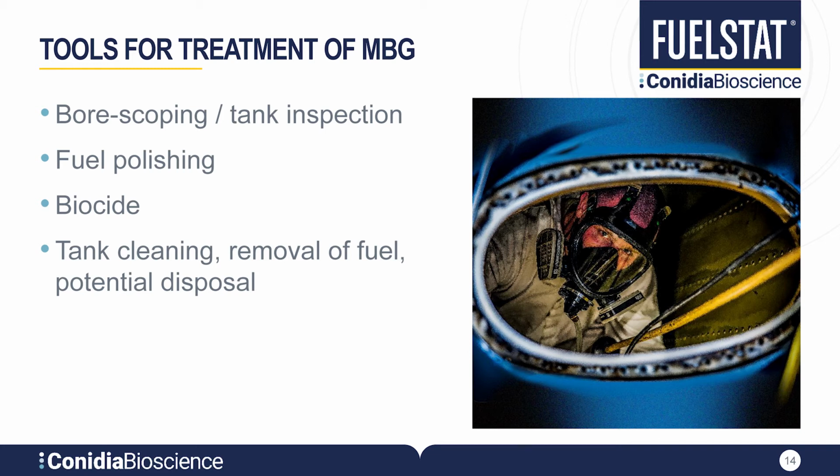The reality is that a combination of both biocide and fuel filtering or polishing would be required, given the biocide will kill off the organisms, but if the debris is still left in the tank, then further issues can occur, so filtering this all out will help.